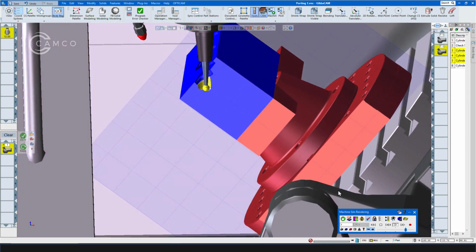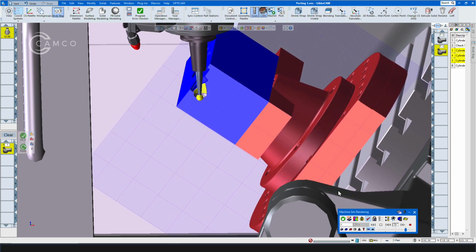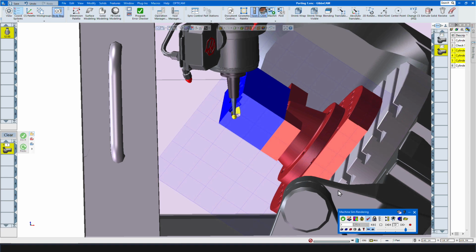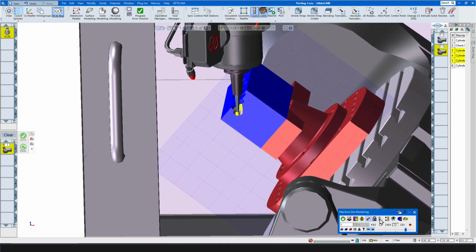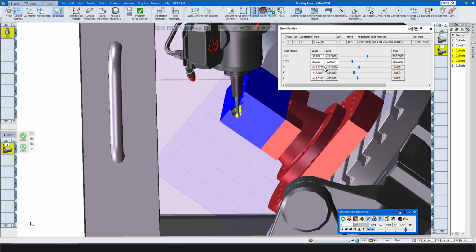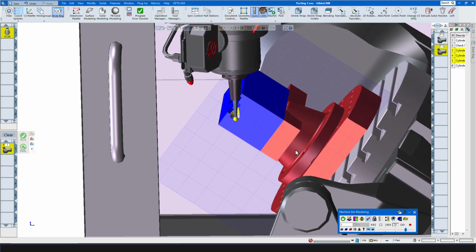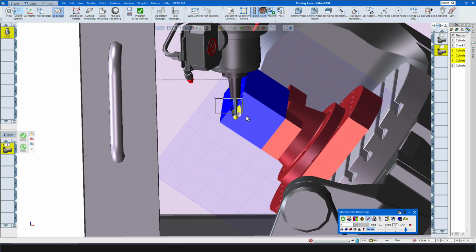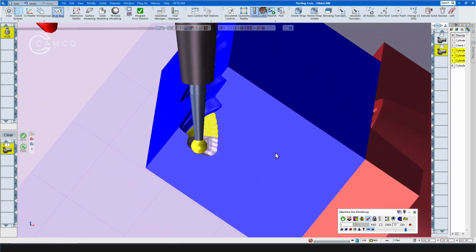We're going to let this toolpath run, and you'll see early on in the toolpath there's not a lot of swing on the rotary axis, but once we get deeper down inside of the port, the rotary axes start to swing quite a bit more in the B and C axis. And as you can see, we are roughing out the material from stock on this particular toolpath.